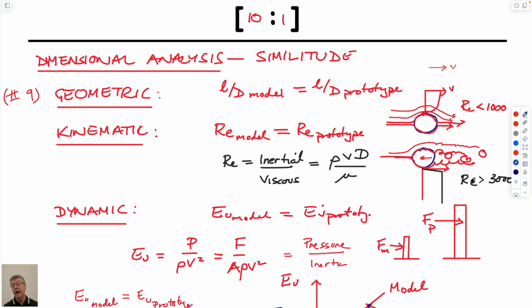If you flow fluids much faster, then the characteristics of the flow system completely change, typically above a Reynolds number of 2,000, as we'll talk about today. And instead of having this smooth flow, it breaks into this turbulent flow, just like the pipe flow that we looked at before with this undulation. And if you think of this as a bridge deck, actually, the circular section bridge deck, this is exactly what's happening that gives the plucking of the deck so you get resonance. You get a vortex shed from the top, and then you get one shed from the bottom, and so that's just like plucking the bridge deck in some kind of frequency. And this frequency is controlled by the velocity of the flow across it and the viscosity of the fluids.